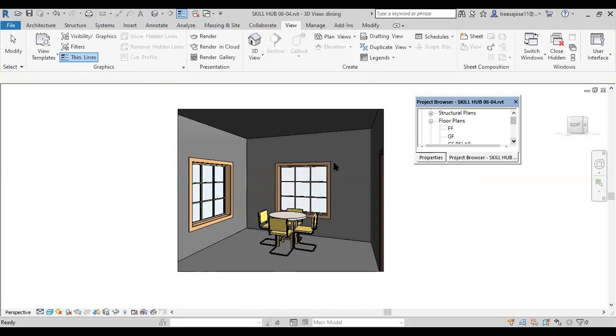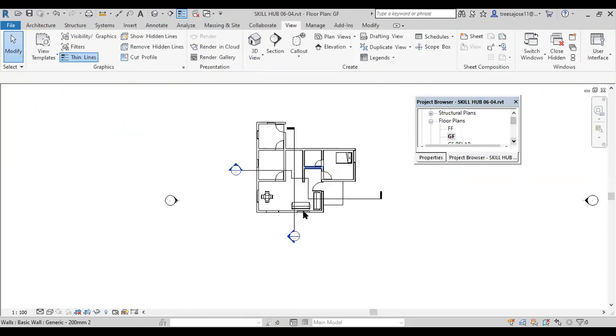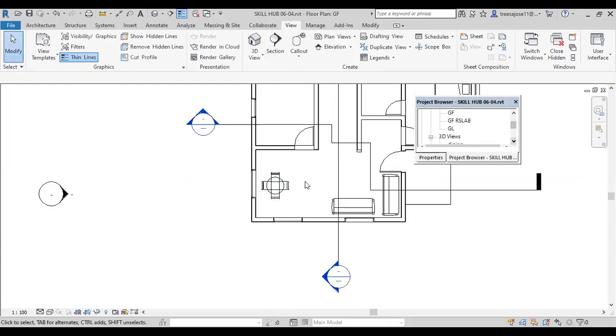3D views. For a section, you have to create a line. Then, in the case of elevation, by default we have north, south, east, and west. Sometimes in your system, maybe the north side elevation is gone, or you cannot have the south side or west or something like this. Moreover, I have to see the elevation, because for details, for example, I have to see the elevation of this row. That time, in the View tab, there is an option, Elevation.